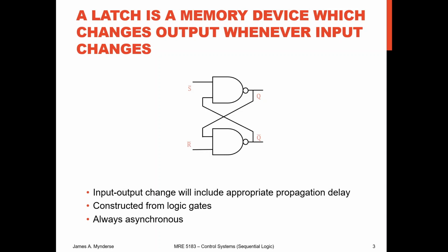And you can see that this is constructed from basic logic gates. In fact, these are NAND gates, although we'll also use NOR gates later. So there's no clock signal, which is what we mean by it being asynchronous. There's nothing to synchronize the input and the output.